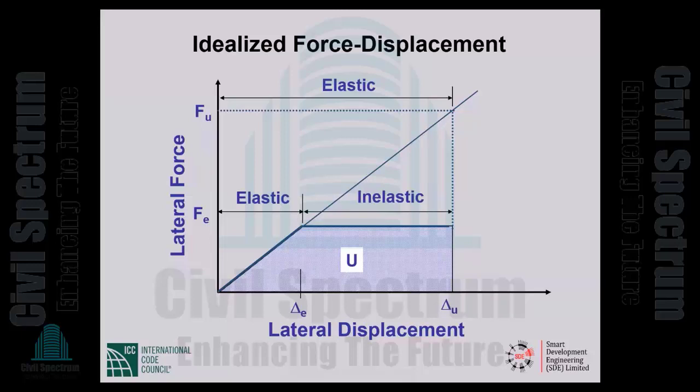The two go hand in hand. The design forces without the detailing requirements have never made any sense. And the bridge between the two, the design force level and the detailing, what kind of detailing we have to do, is the R factor that we will talk about in this presentation.